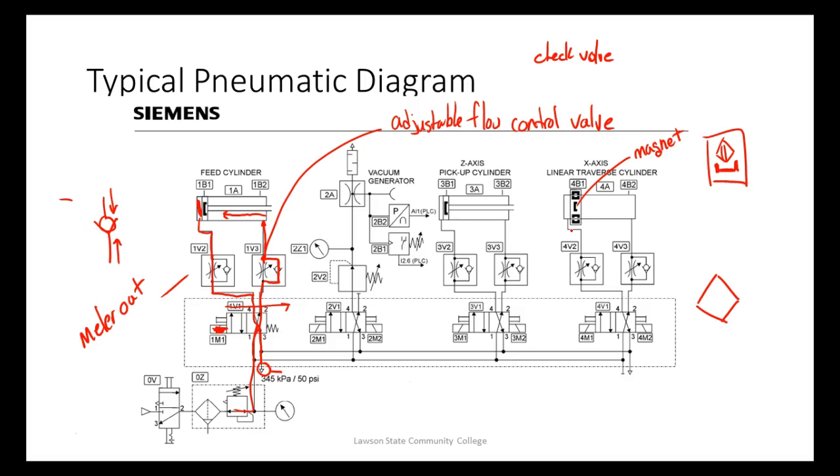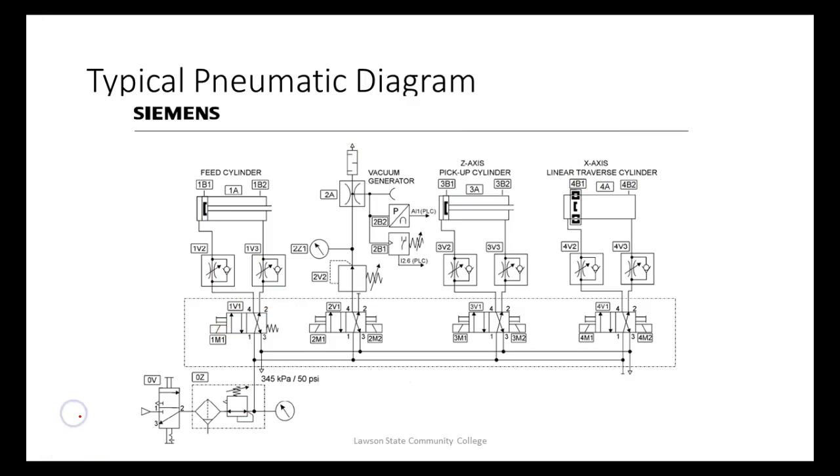And it's pneumatics. So in pneumatics, the metal that we use on these things is going to be aluminum. Aluminum has very little effect on magnetic fields. So what that means is I can put a magnetic sensor right there, right? Like a Hall effect, or I can use a reed switch to sense when the thing is either extended or retracted or wherever I want it to. So every one of these cylinders has magnets in them. Are we okay? Any questions so far?